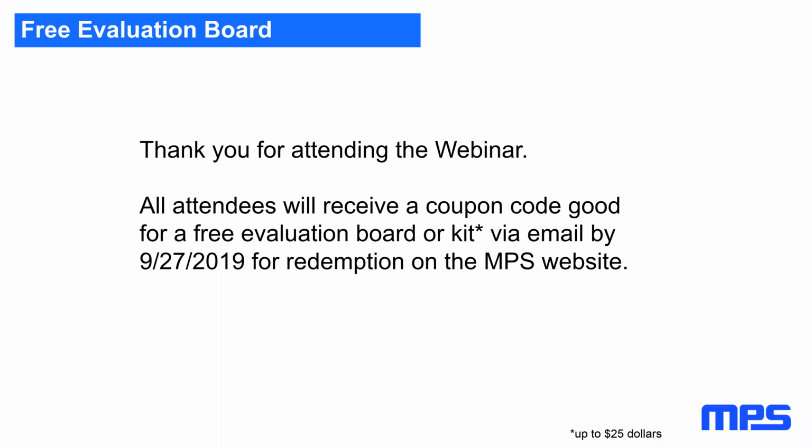How does the trace thickness affect EMI? Extremely little, because if you look at the skin effect, above about 15 megahertz it doesn't matter if you have 2 ounce, 1 ounce or half ounce copper, because the high frequency currents will concentrate on the skin on the outside, because that's the meaning of skin effect.